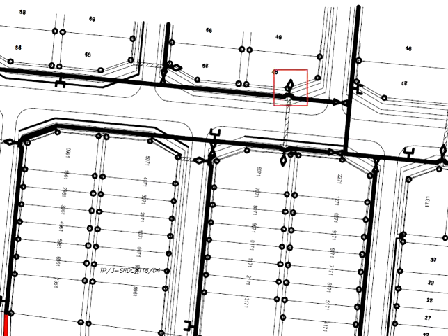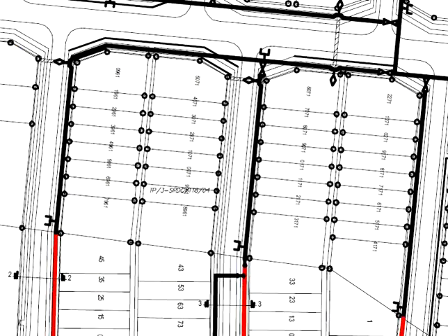The air valve normally comes when there is a change of elevations in the water mains. That's why whenever passing through the culverts, you will see one air valve.